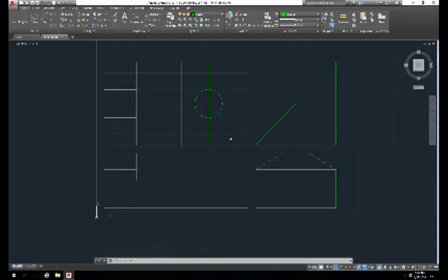But at this point, I have the line from this point. Turn off the ortho for now, to this point. See, I'm going to do intersection to make sure that I'm doing the right stuff. So I'm going to do another line. I'm going to do intersection. You see it gives me a cross, and I'm going to do another intersection. That's like doing a one-off OSNAP definition.